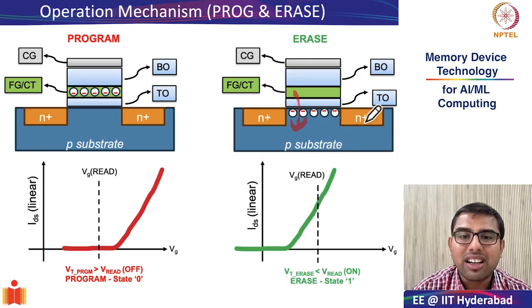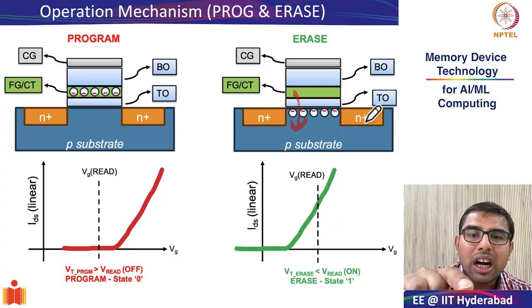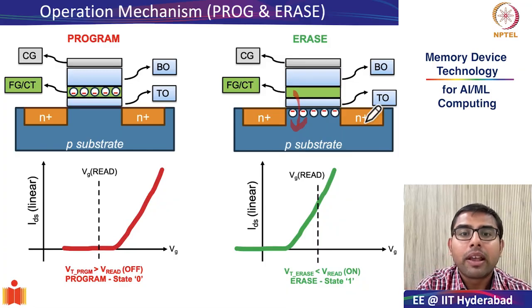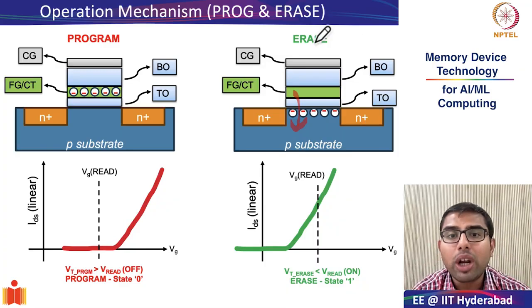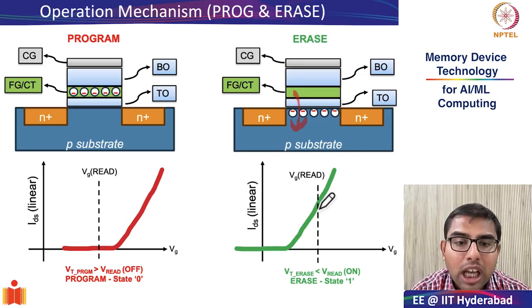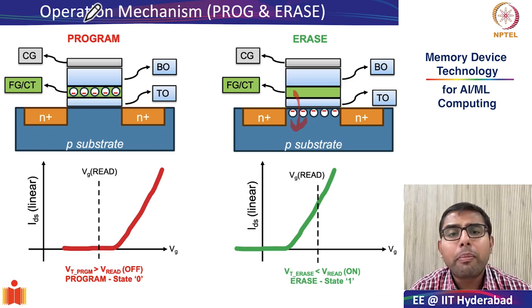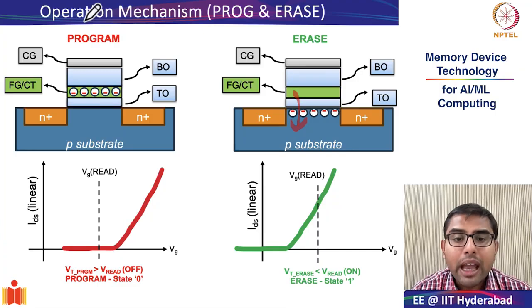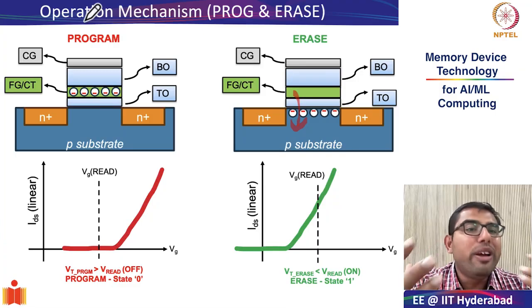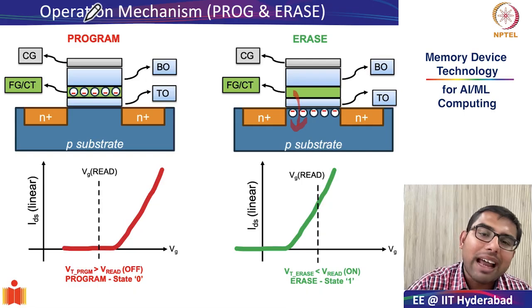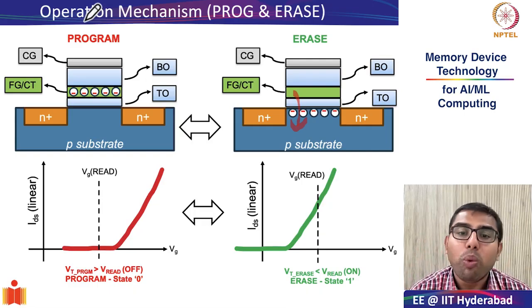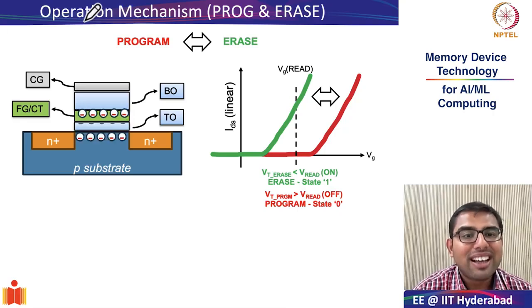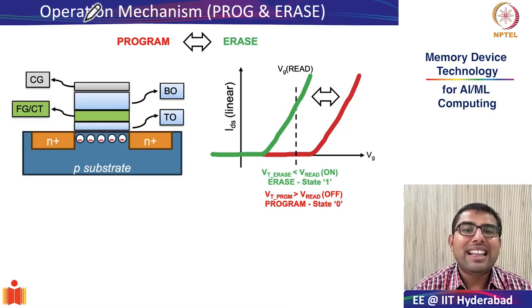As a result, the threshold voltage of a flash cell which has undergone an erase operation will of course be much lesser as compared to that in the program operation, by virtue of the fact that it will behave more like an ideal cell with no trapped charges. Since these are not two different structures but operations happening in the same structure, it may be worthwhile to integrate both of them in the same schematic.